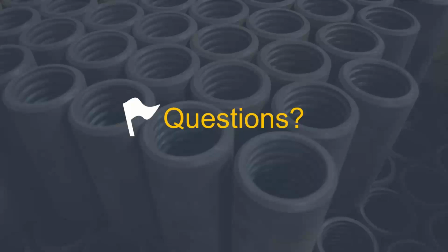It's probably going to support your vertical loads just fine, but there may be some less than desirable outcomes over time, stability issues that you may experience by doing it this way. And it's not to say every time you will experience those problems, but you're basically opening the door for those problems to happen when your pile caps aren't braced in both directions.